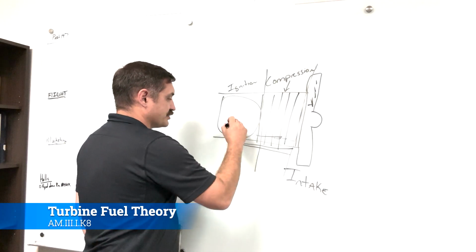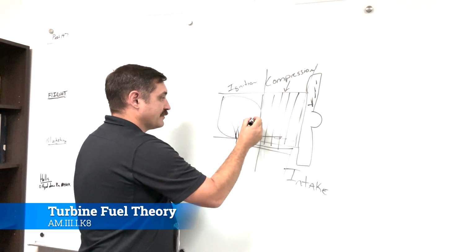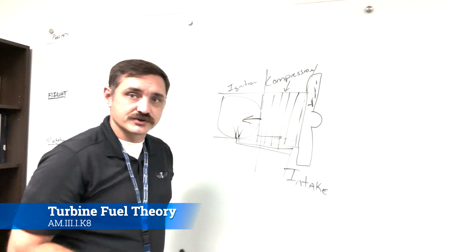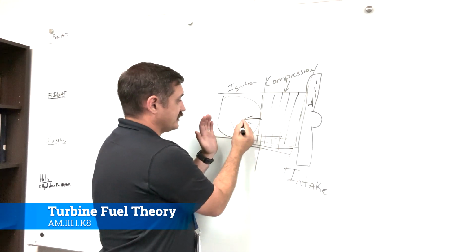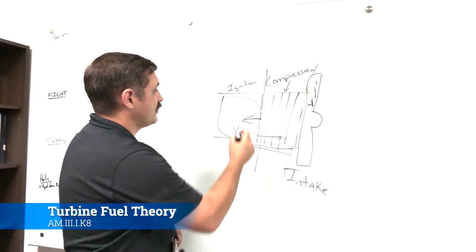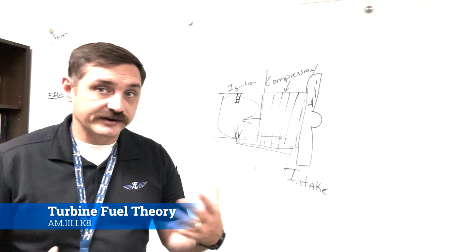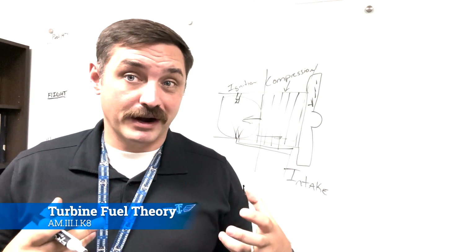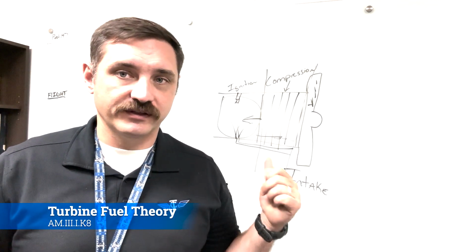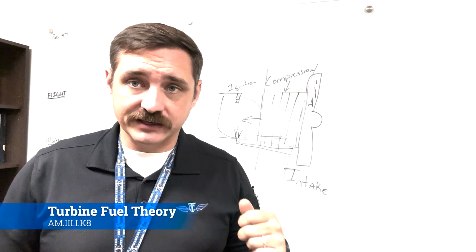But that fuel sprays into here like this. And then you have this hyper compressed air that's coming in from the compressor scrolls, right? So as it comes in, you have air and fuel mixing together, and then you have igniters that sit right there. Now, what's an igniter? An igniter is basically a really big, super powerful spark plug, and whenever the igniters kick off, you'll hear it on the ground because that's how strong that electricity is.